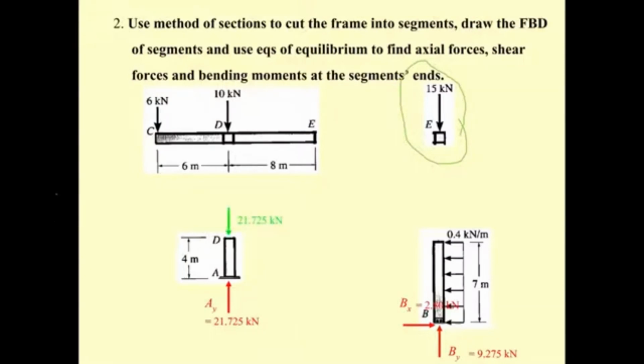And then if we start over here, okay, we have the force over here. For the force over here, we just take summation of F sub y equal to 0. You will get this force equal to this, and there is no shear, no moment, since there are only 2 forces here. This is a 2-force member per se, and then this force is going to transfer to act at the point D. Okay, and the E is going to have 3 forces: normal force, shear force, and moment.